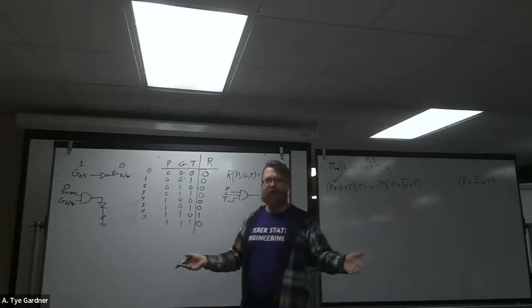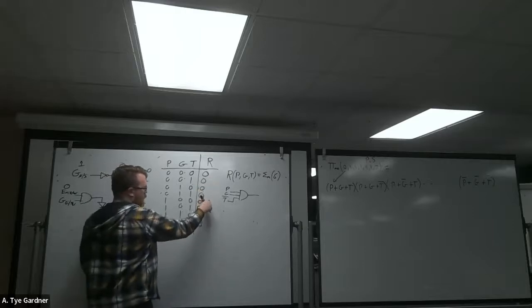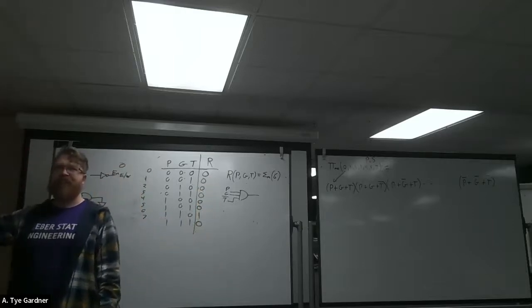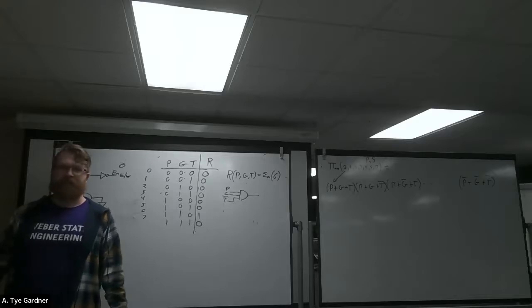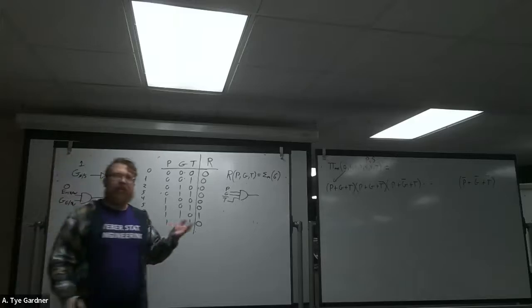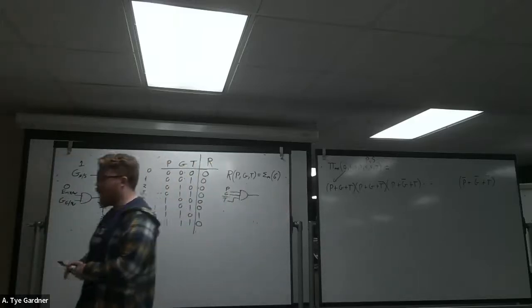Right, one of those is the right choice. If you had the other one, which would be 1 1 1 1 1 1 0 1, right? If we had the inverse of this, if that's what we were designing, then we would probably want to choose the max terms, because then I would end up with only 1 OR gate, which is much better, right? So there is a right thing to choose as far as designing your circuit, and there is a reason that you might choose one over the other.